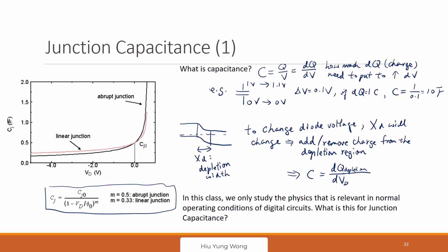So you're almost there. Right, so maybe now it becomes messy. Let's call this 1, this 2, and then I have another 3. Now you tell me, for large reverse bias, X_D is large or small? It's large, right? So when it is large, capacitance has another definition, epsilon divided by X_D, right? Because you are adding the charge across this.